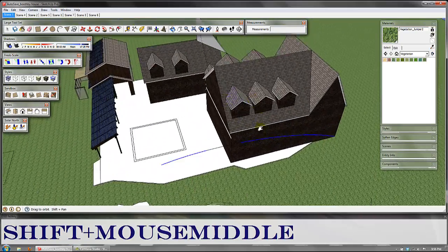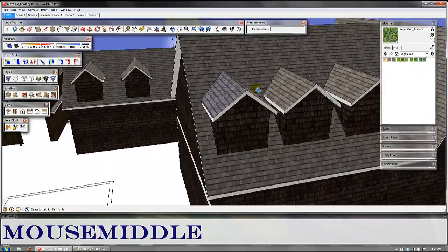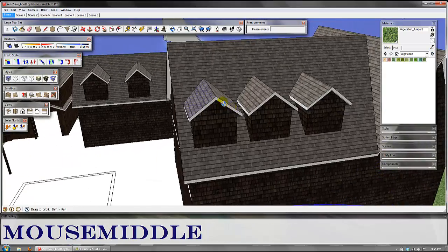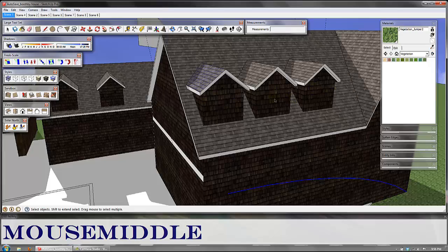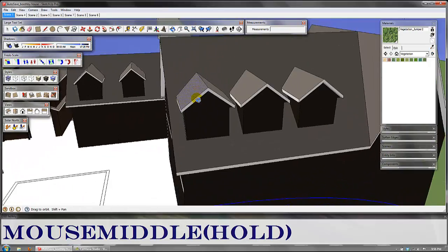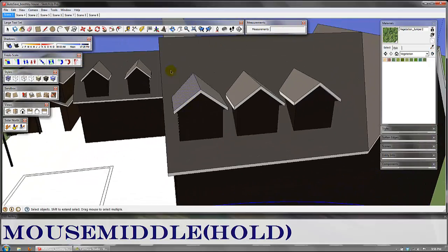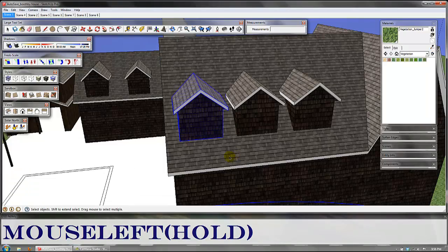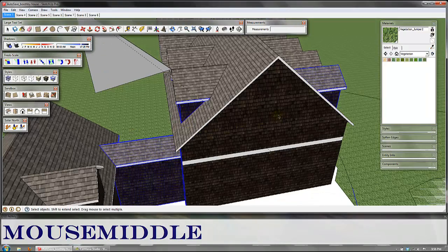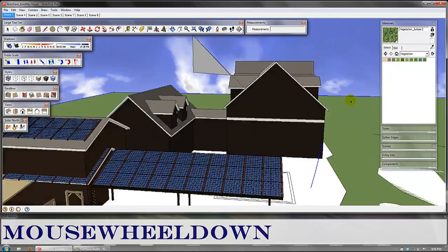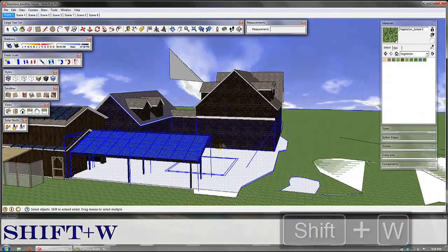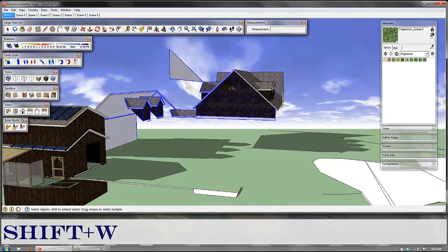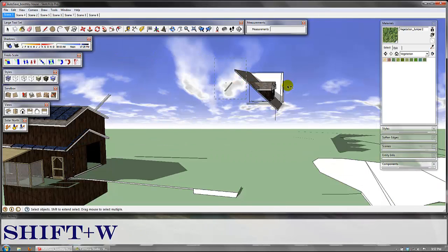This whole house is built kind of with sticky geometry. Nothing is grouped. But what if I want to group this dormer right here and copy it and make copies of these three? It's easy to do. And if you try and just select it like this, you're going to grab some other geometry behind it and you're going to get frustrated. So this is how I do it. And it's done with the hide tool. First, I just start selecting everything that's in its way out of there.